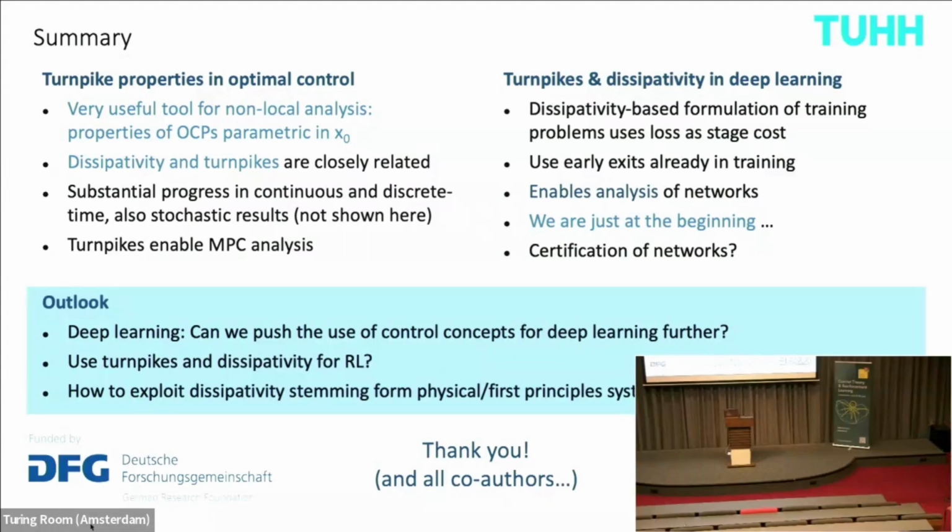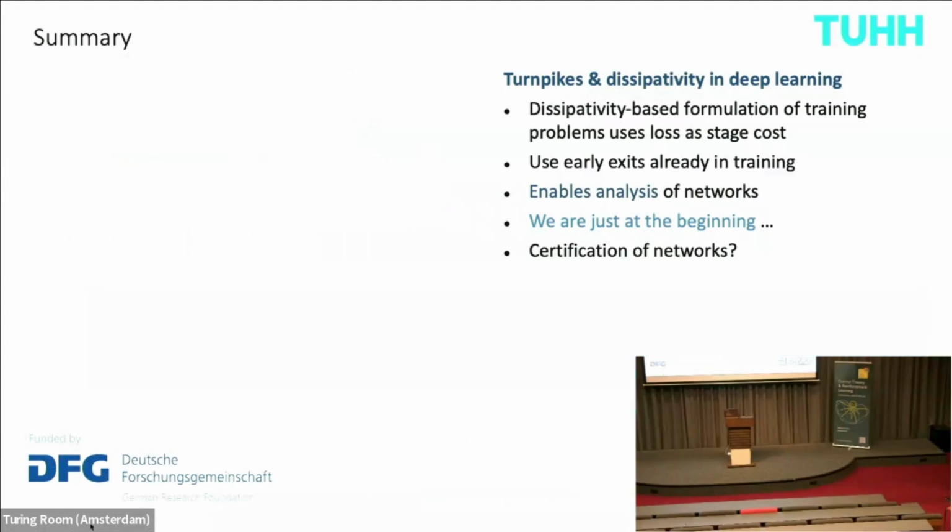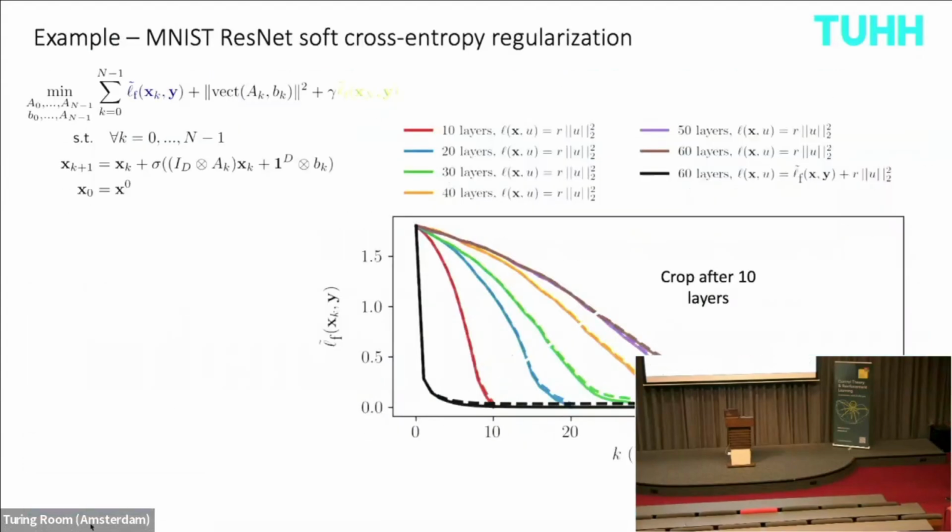Yeah, so if you look at discrete time optimal control, it does not make the numerical integration issues go away. It's still there. And there are two main phenomena in this backward integration. One is this instability, the other one is this decay of sensitivity. And when we started discussing whether we can use turnpikes, colleagues and co-authors on some of the papers said, you don't want to have that. Nothing happens here. That's decay of sensitivity. That's not how it's supposed to look. And it took us a while to understand that we can use this to our advantage and say, let's cut there.